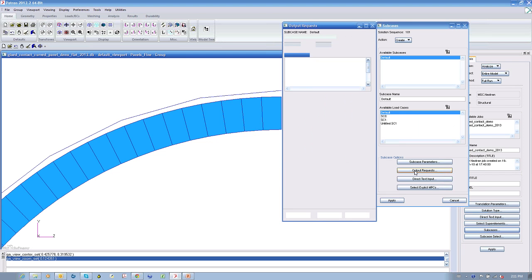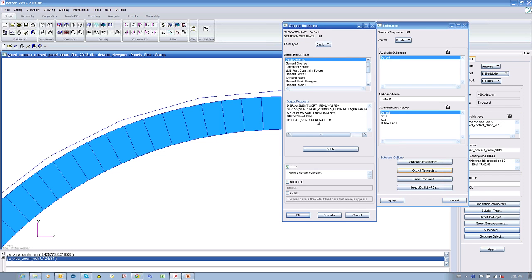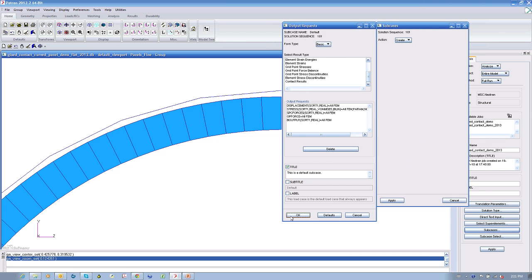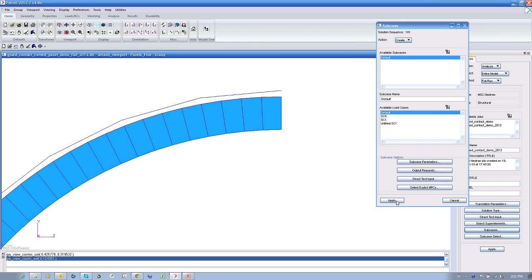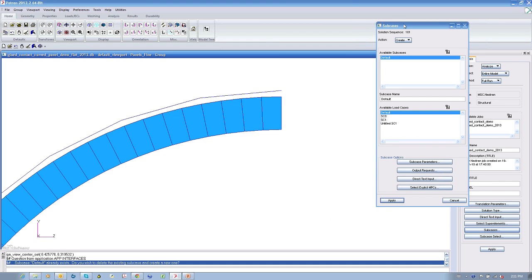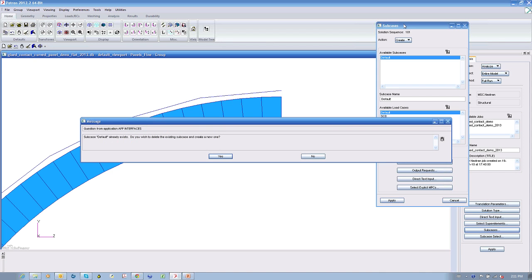Let's make sure that we have B output. So there's an option to select here what we call B output, which is the contact results. This is what is going to trigger the output for generating contact results, just to verify that everything touches initially on our run.